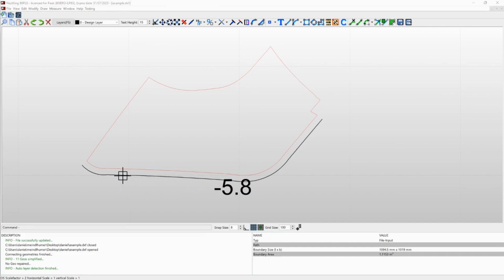So this line is on the wrong layer, therefore we can switch the layer. As already stated before, we want to have layer 3. We can also change the layer by just selecting the geometry and pressing key 3. This is number 3 on the keyboard itself. If you press 2, layer 2 will be activated, layer 1 is the text layer, layer 0 design layer, and so on. But in this case we want to have layer 3. This one should be on layer 0.